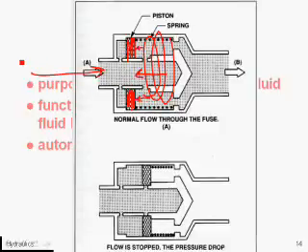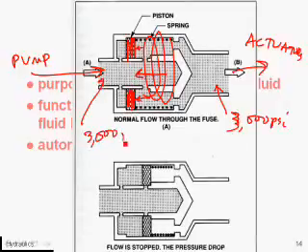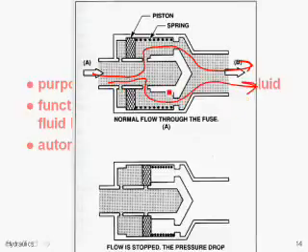Now, here's fluid coming from the pump and fluid going out to the actuators and selector valves. Now, the pressure in here is really, really close to 3,000 psi, and the pressure in here is 3,000 psi. So the pressure on one side of this plate is 3,000. The pressure on the other side of the plate is 3,000. But oh wait, here's this spring, so that overcomes the equilibrium and pushes this plate over. So now the only way the fluid can go is through this hole right here and this hole right here, and it works out just fine. Slows the fluid down a little bit, but it's not too bad.